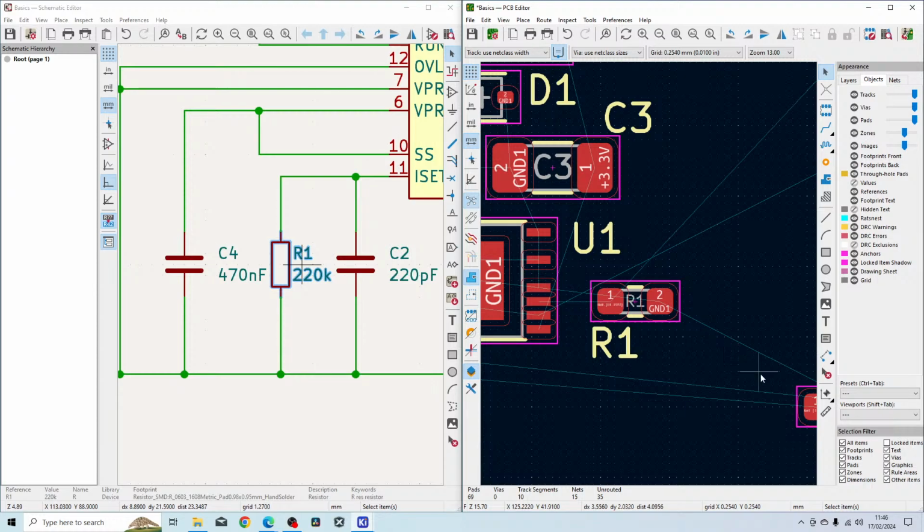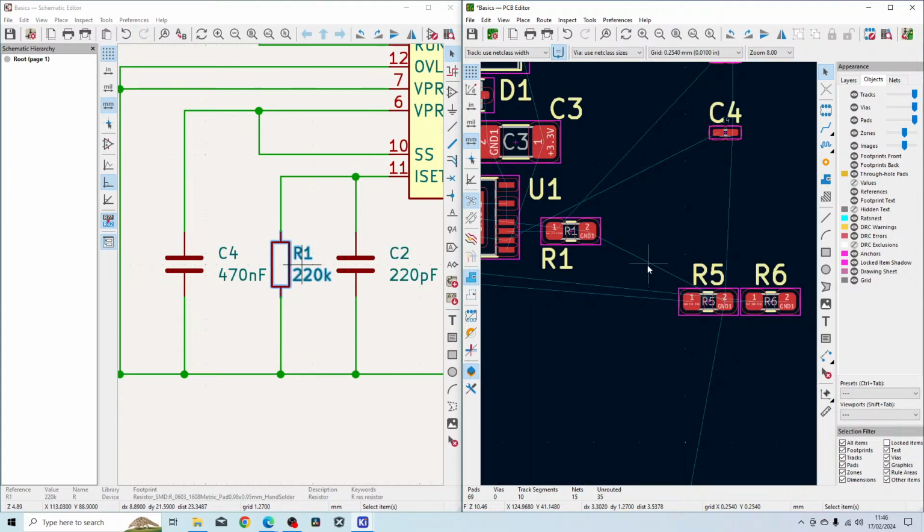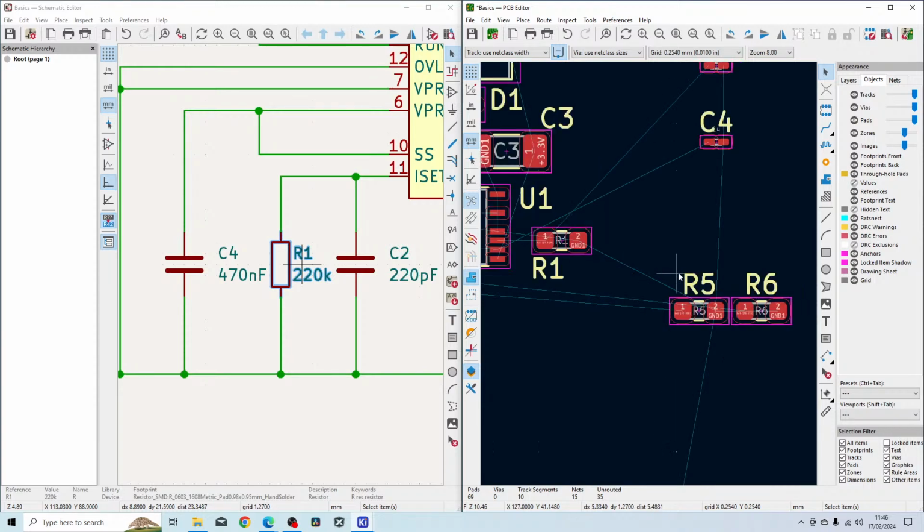Oh yes, for DDR, there are many different things that are quite important. Some of the things like your track characteristic impedance, your load impedance. Obviously, you want to have clearances to nearby parts. You want to make sure that the track lengths are the same, so then you don't get much propagation delay.